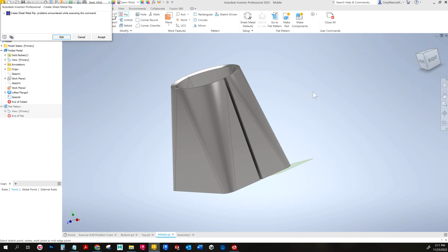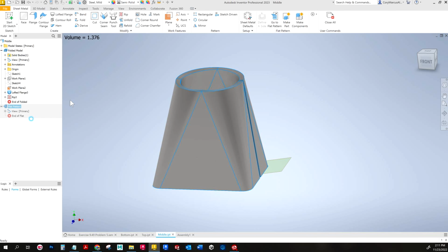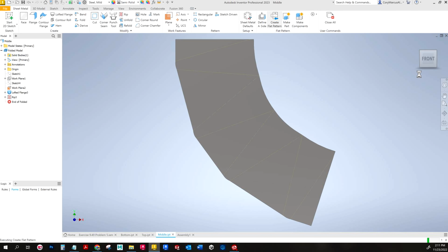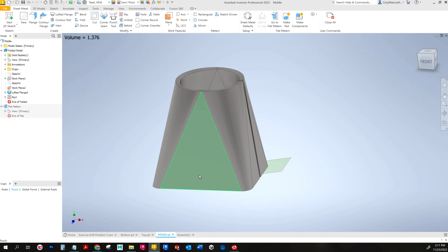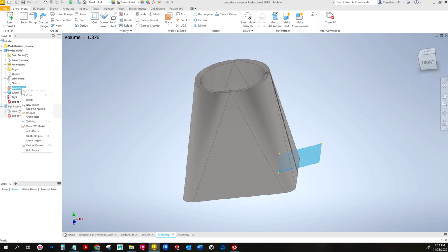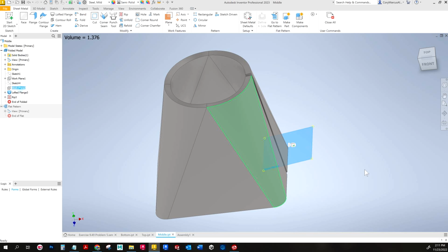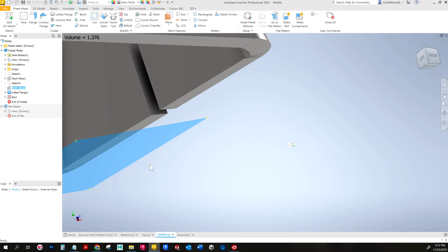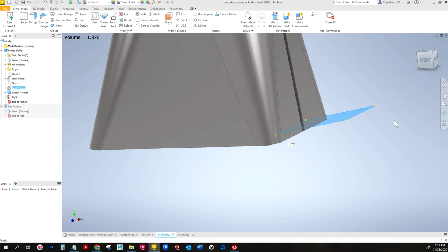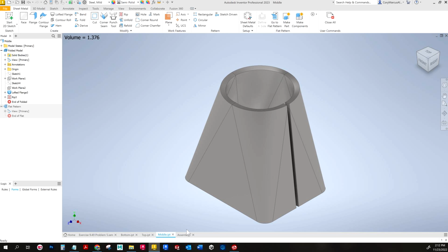And it still works the same as you see. The error is in regard to the flat pattern. So I'm going to delete that and recreate it. Make sure when you're reading those prompts that you look. Sometimes it's actually not a big deal. So what's funny is this new plane was created because I clicked the face and I got a weird spot. That's fine. It still leads to a rip. Ultimately, as long as it rips, it really doesn't matter too much.